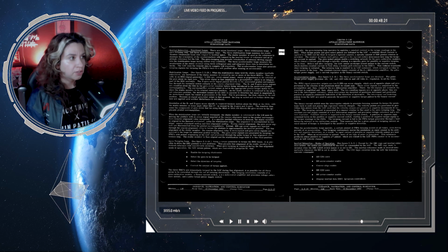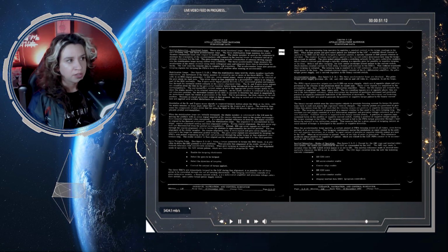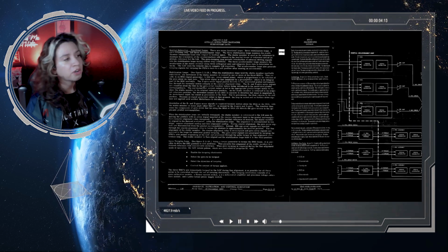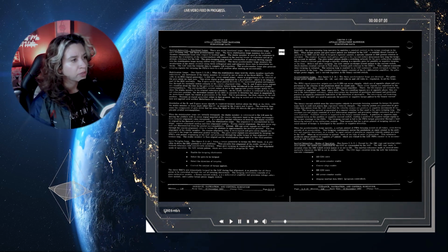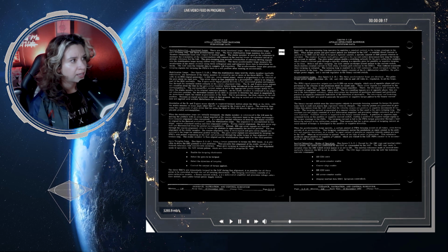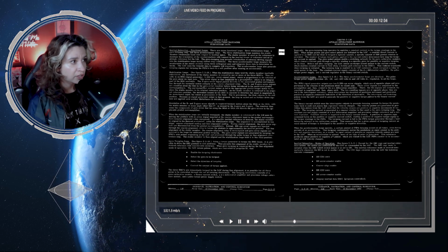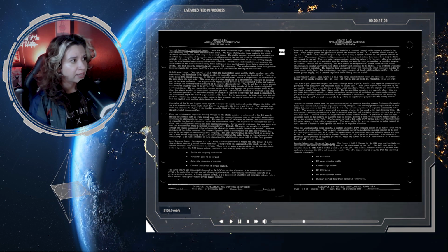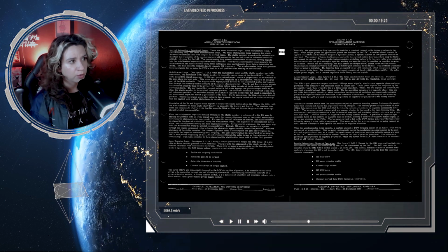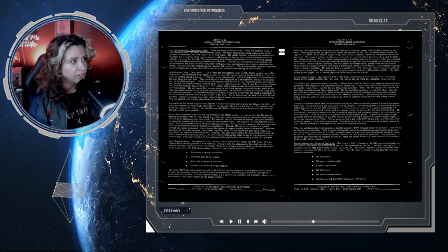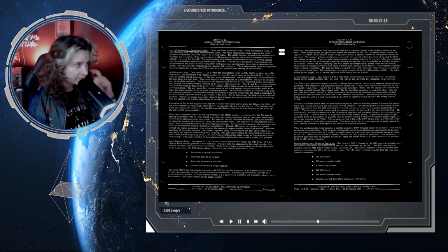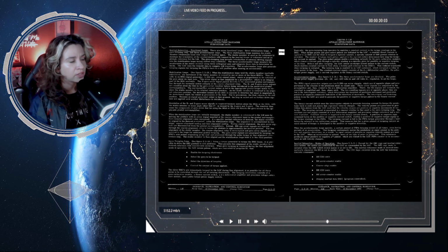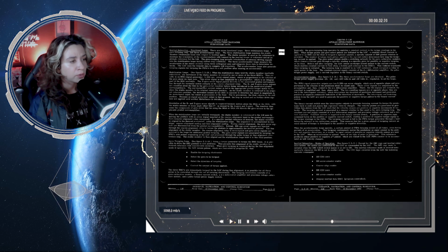The inertial subsection and functional loops. There are seven functional loops: 3 stabilization loops, a gyro torquing loop, and 3 accelerometer loops. The 3 stabilization loops maintain the stable member rotationally fixed with respect to inertial space, and the stable member is used to reference and maintain the orientation of the accelerometers with respect to the inertial frame of reference as the attitude reference for the LM. The gyro torquing loop permits introduction of external driving signals into stabilization loops during closed loop conditions.